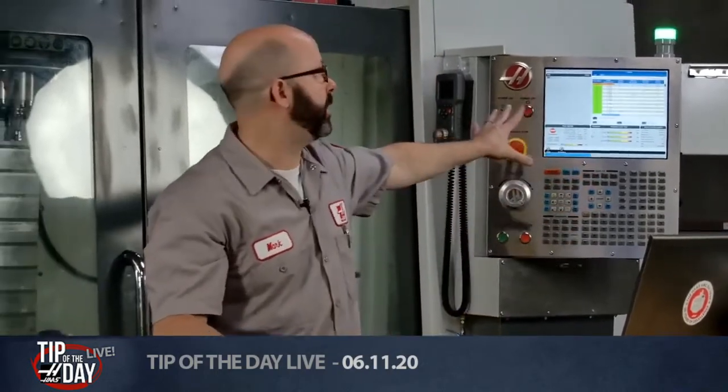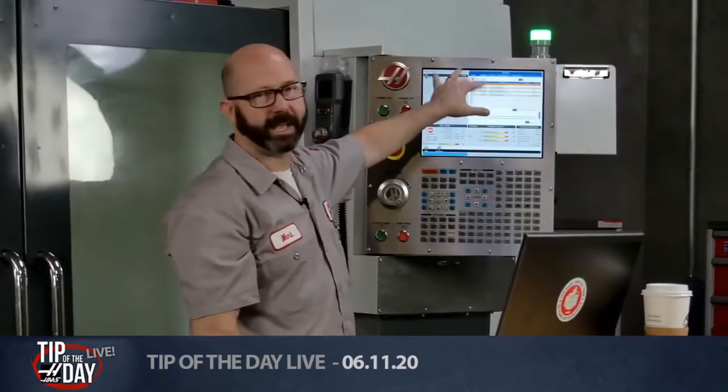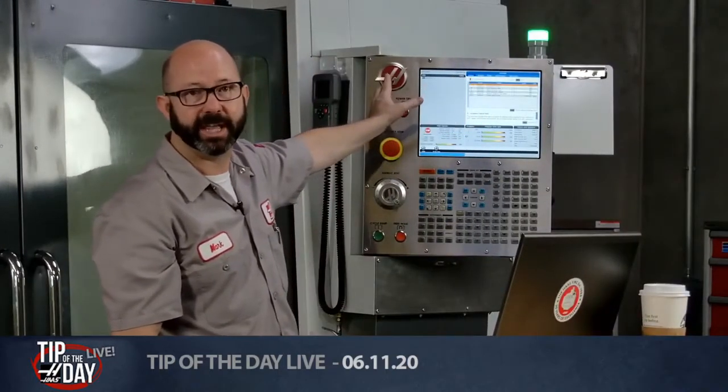So it's really kind of cool. There's some settings on the control. If you type in M99, it'll say M99 bumps M30 counter, but what is the M30 counter? As far as a macro variable goes, it's pound 3901. So we've got two M30 counters for you that you can use, and they're separate from each other. 3901 is the only one I remember. I don't know if it's 3901 and 3902 or 3900 and 3901.